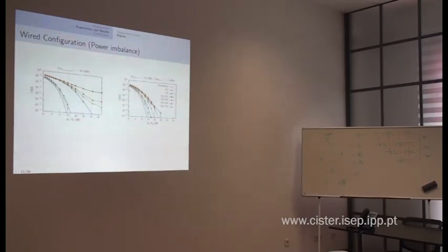But if you start to put more nodes, so that they concurrently transmit, and the amplitudes are made the same, because they are programmed to transmit to the same power, then we start to have these flat curves here, which say that there are a lot of errors. Even when you increase the signal to noise ratio a lot, you still get a lot of errors. And that's what's happening when the signal becomes so vulnerable when it has a depression that even a small amount of noise can interfere.